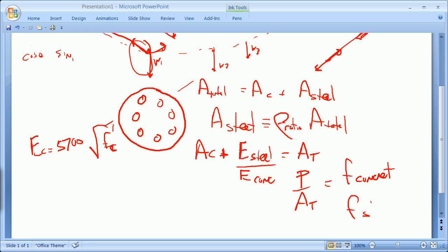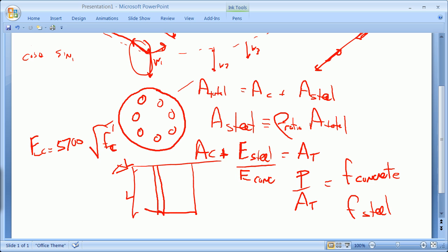And the stress in the steel is just the stress in the concrete times that ratio reversed, so it's something like 9 times that of the concrete. And that's because if you look at this in cross-section, if this section changes from L to delta L, the steel is also changing from L to delta L. And delta L over L is the same as strain. You know that strain times the modulus of elasticity of steel is equal to stress. So that's how that mathematics goes.